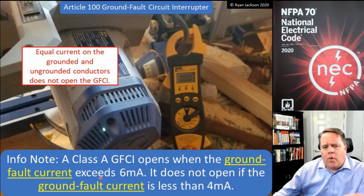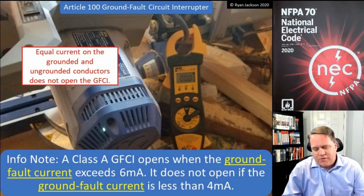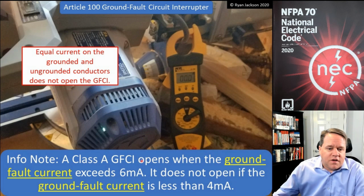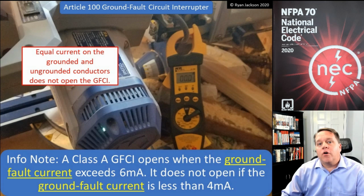Why does it trip when we exceed 6 milliamps? And why do we want to make sure it doesn't trip when it's less than 4? Well, because less than 4 milliamps really isn't going to kill anybody. More than 6 milliamps could result in a painful shock. How do we know this?